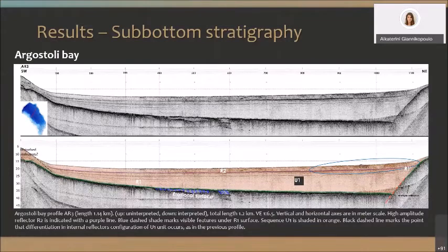Seafloor is mostly horizontal. The reflective surface R1, noted in green color, begins with a steep slope to its southwestern side, continues straight with a slight downwards inclination to the northeast, and it appears to terminate against a very steep surface noted as R1 accent. This feature is thought to be indicative of a fault, noted with a dashed red line.